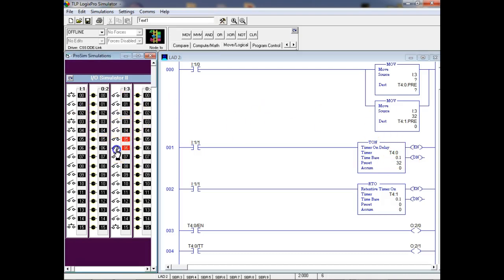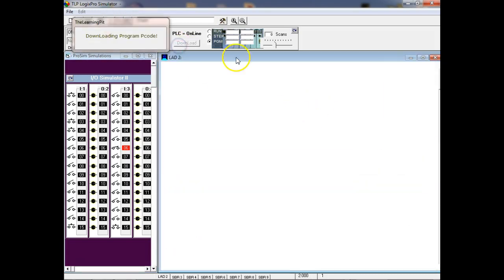You can't say totally it doesn't matter which one you put first. Technically it doesn't, because remember, this thing starts scanning where? Here, then it comes down here and down here. So it might matter, but in our situation, it's not. Does it show somewhere on there that it's retentive or not? Yeah, RTO. Oh, I'm sorry, yes, thank you. Welcome.